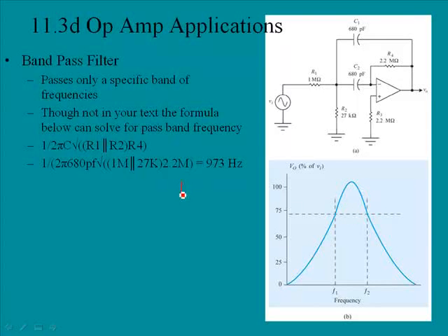This is widely used in TV, also in radio. Just as an example, with AM radio, if you were looking at AM 950 kHz, it comes in, and this would be 950, and that particular band is, in the transmission, 10 kHz wide, and so it would go from 945 to 955, and that would be, in this case, the band that is being passed.